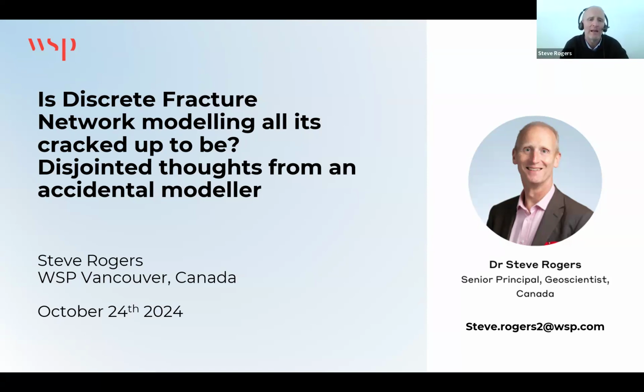I mean, a lot of what I've just shown today, there's no actual dynamic modeling of a fracture. They're kind of static. So say take the slope modeling, the fractures themselves were just modeled as almost forming blocks and they've got some kinematic properties. So they potentially could slide, and the slip surface allowed an equivalent joint to represent rock mass strength. However, within FracMan and within other tools, obviously you could actually have more coupled responses. So actually giving those joints stiffness that will respond, so that the apertures would actually change during loading. But nothing I've shown you today I think you would call a dynamic response.